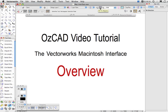This is fit to objects. This will zoom you out so that you can see all of the objects in your drawing. If you have an object or objects selected, then it will zoom in to just those selected objects. This option here allows you to zoom in, or as the shortcut says, zoom out if you press the option key. This one here sets the current zoom of the drawing, and you can also choose a zoom level here. Obviously there are other methods to zoom in and out using the mouse and so on.